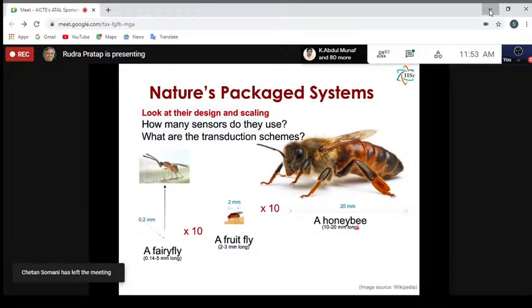C will be the original capacitance minus the capacitance that you get after you move this plate by a tiny amount X, right? Now, if you take the ratio of the two, then you get a pure function on the other side, which is just a function of X, which means that you should be able to find out what the displacement is just from the change in capacitance. And if you can find what the displacement is, you can figure out lots of things, right?